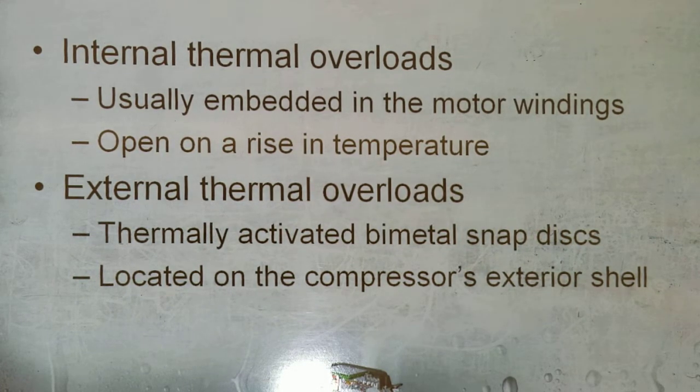External thermal overloads. Thermally activated bimetal snap disc located on the compressor shell, exterior shell. Okay, so the internal, all these motors have internals.